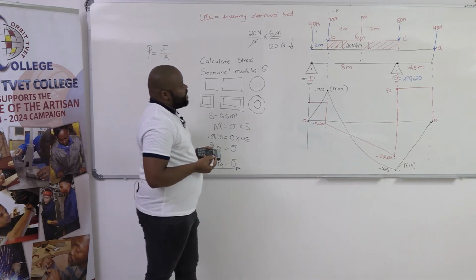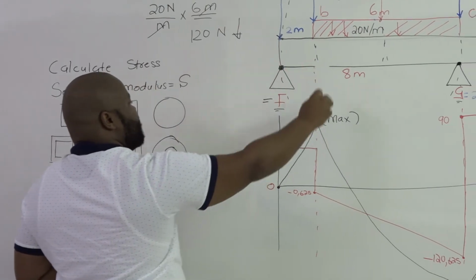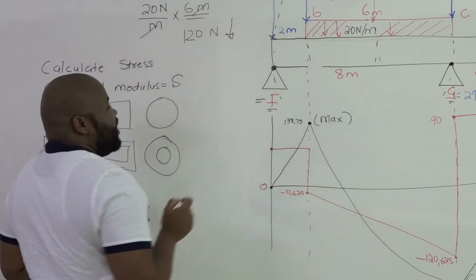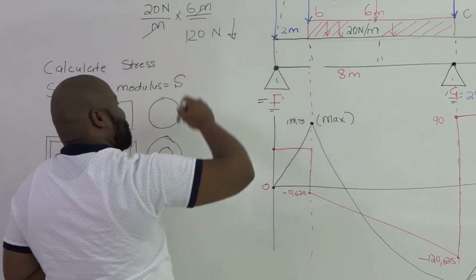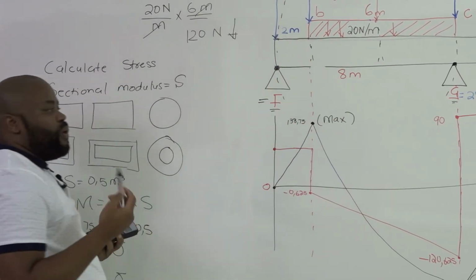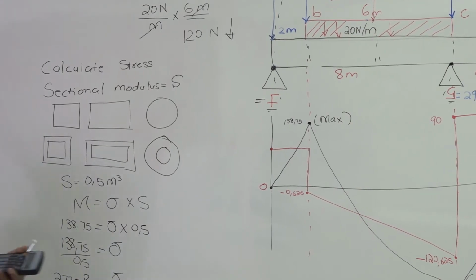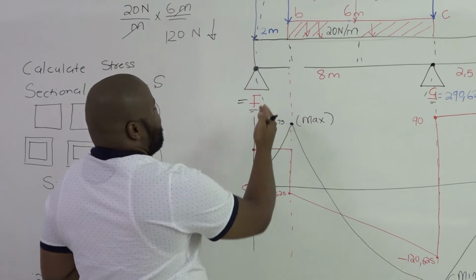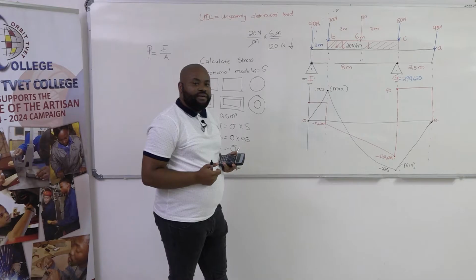Then from there you check which forces from this fulcrum point are going in the clockwise direction and which forces are going in the anti-clockwise direction. The most important information that you must not miss is that the reactions F and G are also forces.